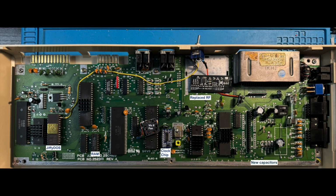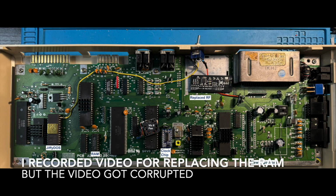And then luckily the other problem was very easy to fix, and that was because one of the RAM chips was really hot, like burning hot. So obviously that was a good indication there's probably a short in it, it's bad. So when I replaced that, everything seemed to work.